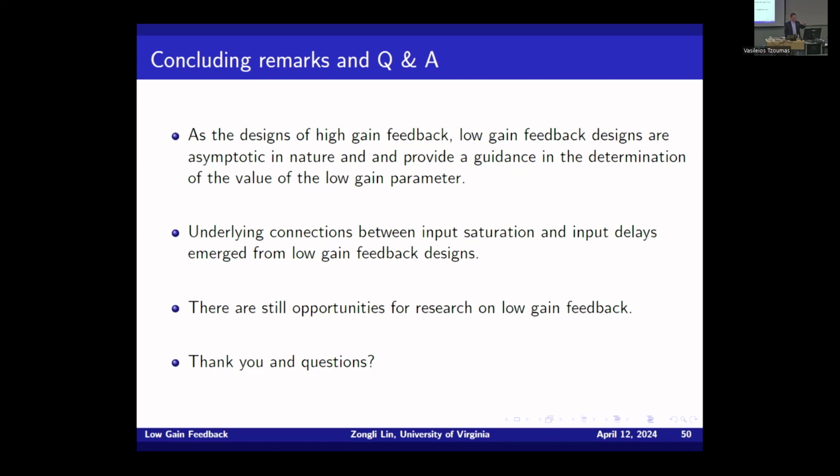This is kind of dual: for state feedback, you want the open loop poles to be in the closed left half plane, but for this, I need all the zeros to be in the closed left half plane. And the idea is I will cause the system to oscillate. Once it oscillates inside the linear region, then the observer will work a little bit, and then it works out. But I can only do it for single input systems. Over time, some of my students tried, and none of them was able to go further.